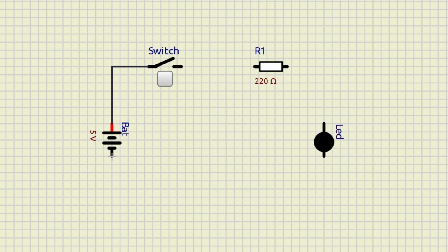Sometimes, while routing a wire, it may not follow the path you want, as shown in the video. If that happens, start creating the connection as usual. Then, whenever you want the wire to change direction, simply click at the point where you want to create a bend. After creating the bend, continue dragging the wire toward the destination and complete the connection. Using this method, complete your schematic.